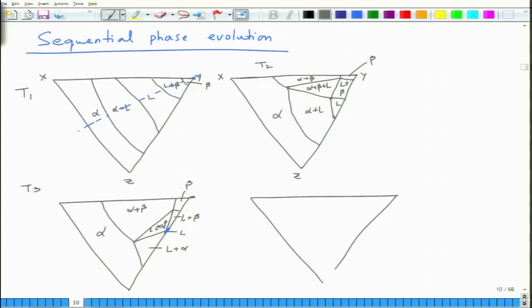below the solidus, so here you are below the solidus, you are now slowly approaching the solidus surfaces. So, your liquid phase field is shrinking and solid phase field is expanding, whether it is alpha or beta, it depends upon where you are, what kind of phase diagram you have. So, eventually what you have is alpha plus beta and then beta. So, this alpha phase, you can see that sequentially you started from liquid surrounded by liquid plus solid surrounded